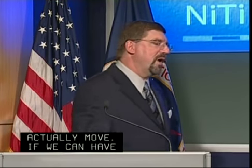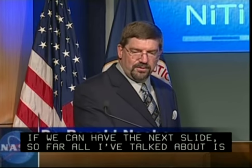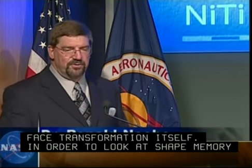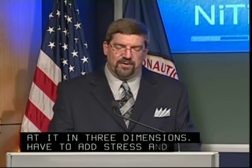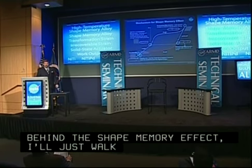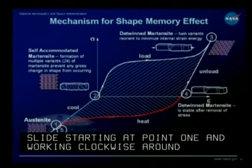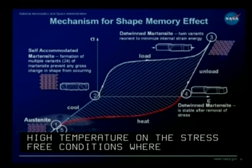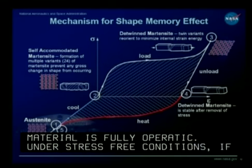So far, all I've talked about is the effect of temperature on the phase transformation itself. But in order to look at the shape memory effect, we have to start looking at it in 3 dimensions. We have to add stress and strain to the equation. And so in order to understand the mechanism behind the shape memory effect, I'll just walk around this slide starting at point 1 and working clockwise around the figure. If we start at point 1, we're at some high temperature under stress-free conditions where the material is fully austenitic. Under those stress-free conditions, if we allow the material to cool, will form what's called self-accommodated martensite.